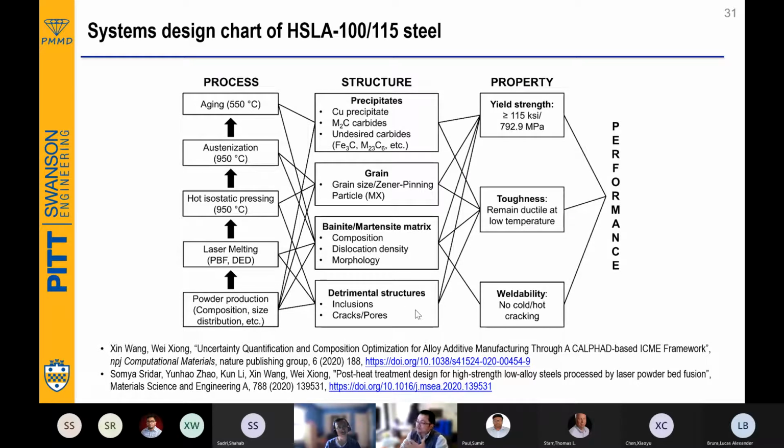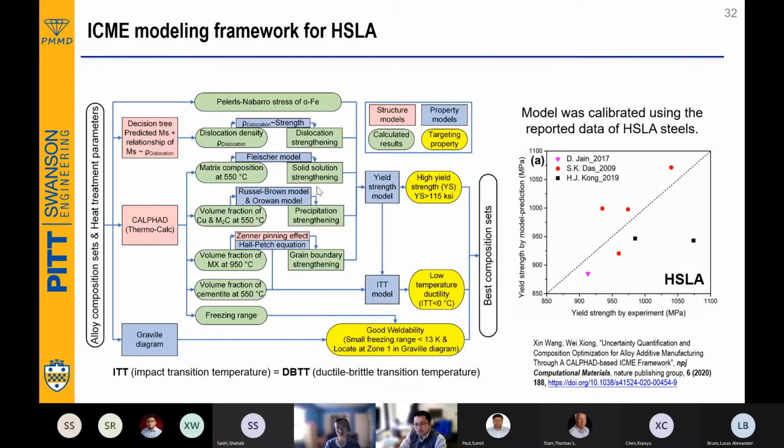Then it's kind of discovery. Discovery is totally different. And then we also care about the quality of the ICME model. You can build thousands of models, but we have two principles. One principle is that such a model can be linked with multi-component cases. That means the model should be based on the alloy composition choices. So you input one composition of the alloy with multiple components, more than 10 elements, and you have to get an output. The second is that you have to calibrate the model.